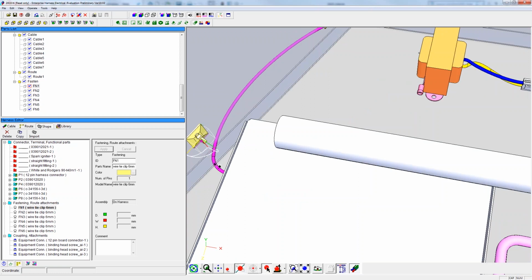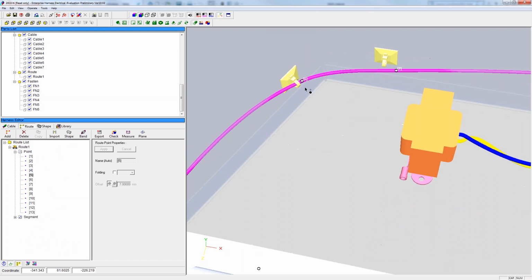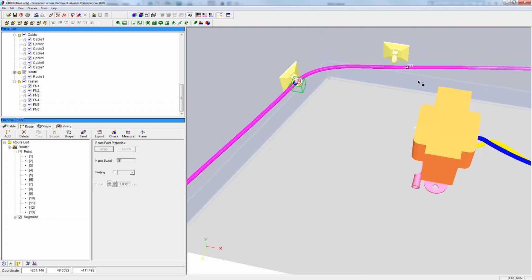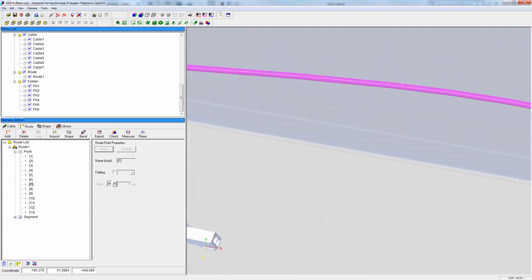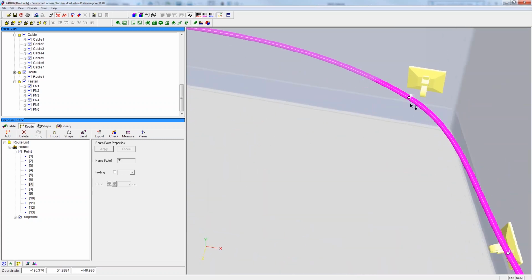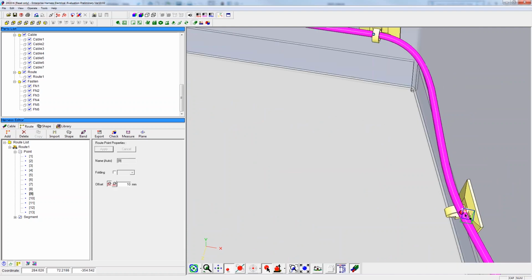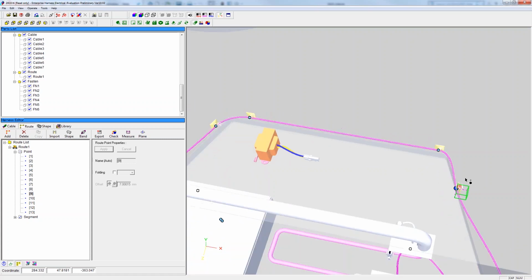But now, the easy part. To manipulate this, just a case of dragging the wire through the connector there. You'll see it line up down axis. That's what we want. And now if I move the clip around, the harness will go with it. And this can just be a lot more controllable. Just like in real life, you want it to be controllable, you want it to be locked to geometry.